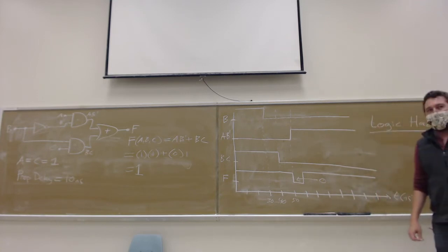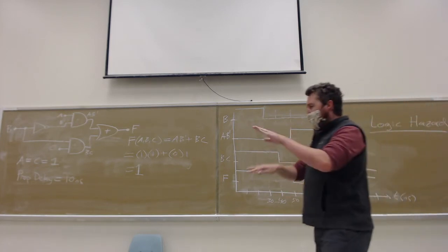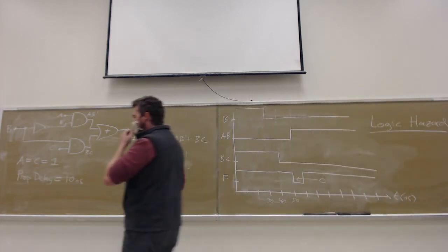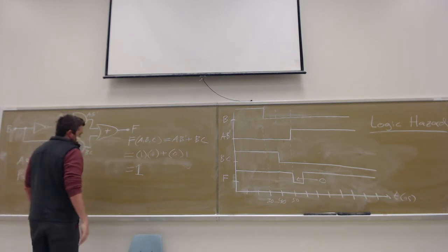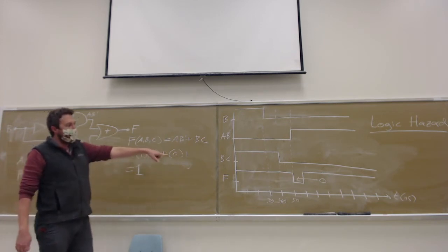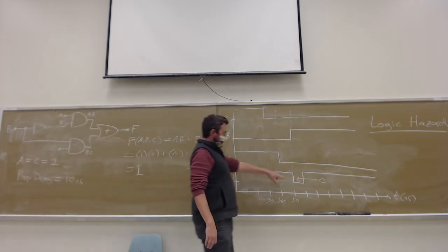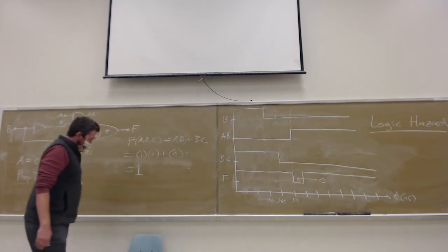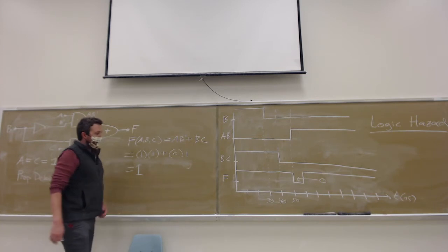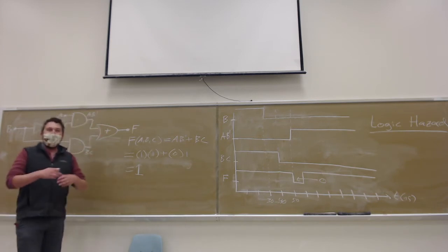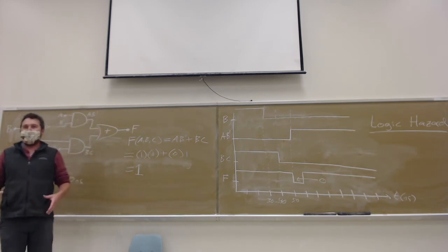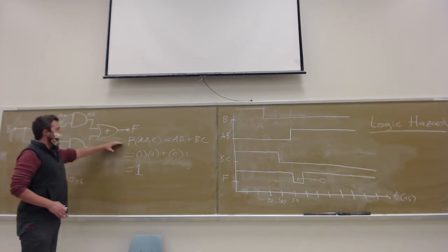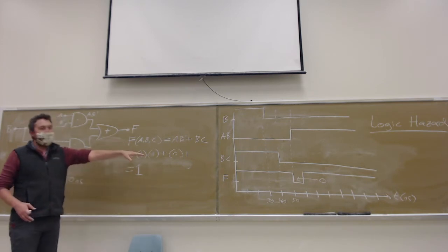It's when, because of the way the timing is set up, the way propagation delays play out, a circuit can momentarily give outputs that are not what you intended. So F should never be going to 0. Yeah, by all of the rules that we've talked about so far in this class, when we set our inputs the way they were, F should have stayed at 0.